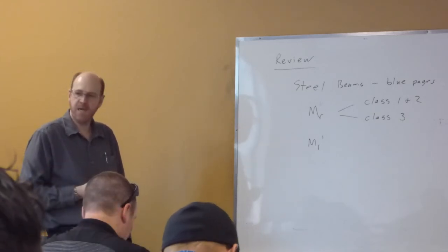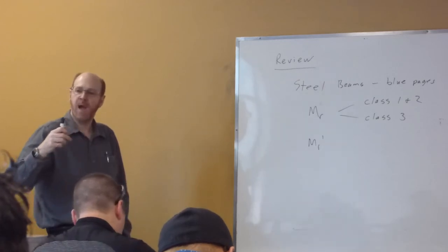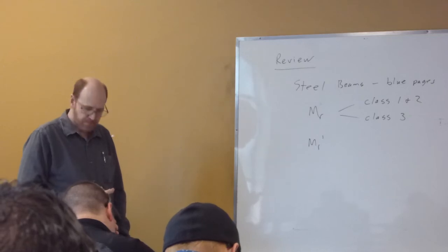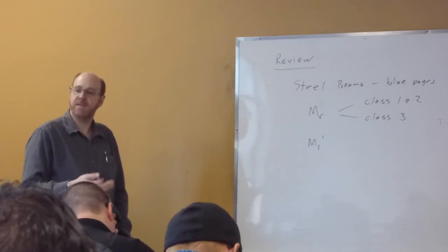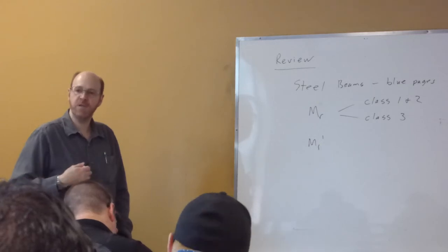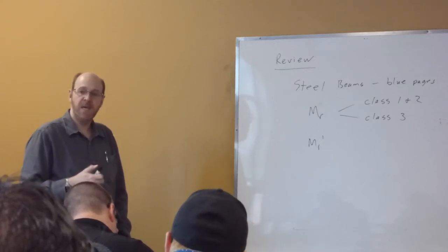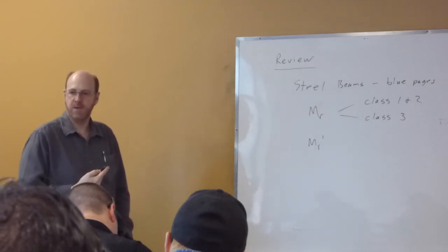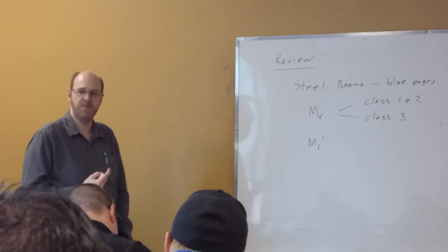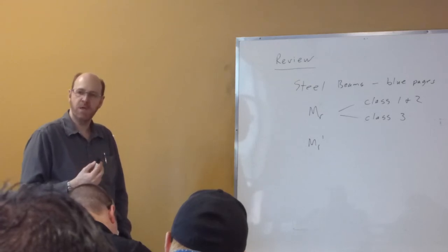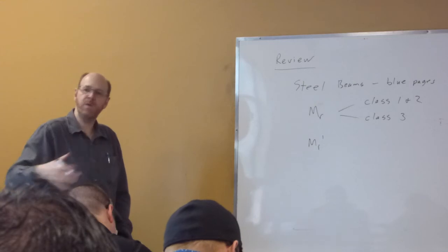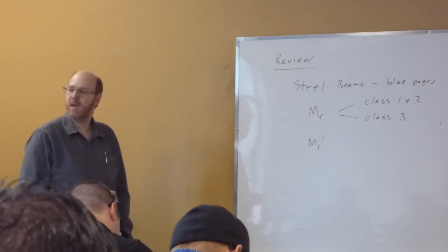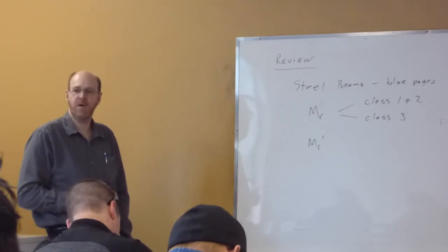Right, so we looked at the first stage, so the columns have been erected, and we have some beams that go between the columns, and those beams, we're designing like a simply supported connection based on our full service load. Right, that hasn't really changed. It's these beams that span between the beams that are kind of running like joists. Right, so there's smaller beams that span between the main beams. So when we're looking at the design of those, we're looking at a construction load case where we've got a steel deck and we're laying it on top. And we have a couple of workers that are on top in order to be able to weld through and connect that steel deck onto the beam.